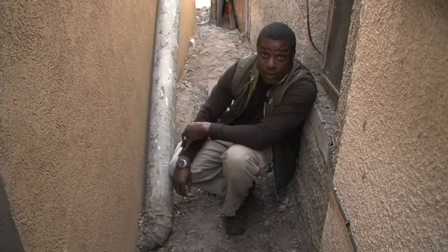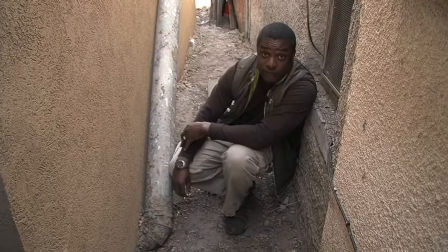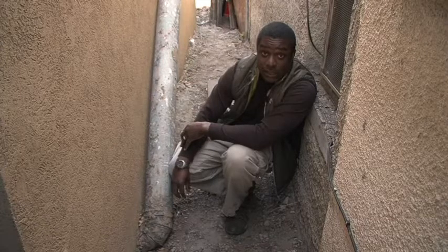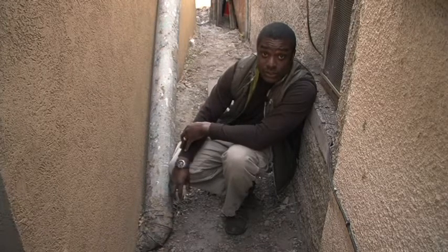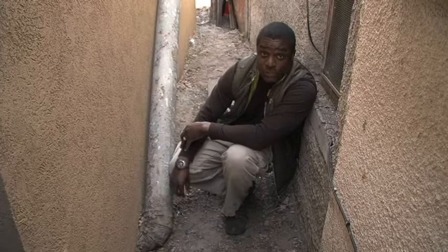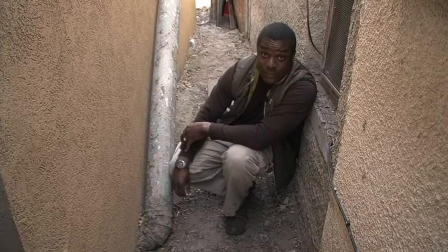When we were doing our walk around, we ran across this flue pipe with a long run outside exposed to the elements. What that's going to do is cause an excessive cooling of the combustion gases. So likely when we get inside, we're going to find a water heater and a furnace that are having a hard time drafting.